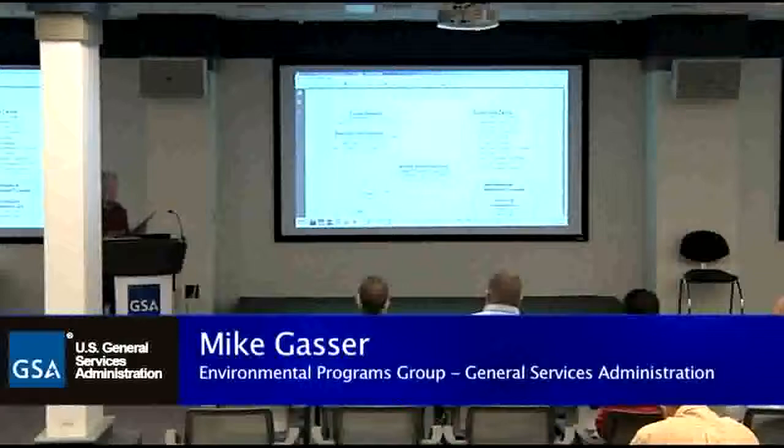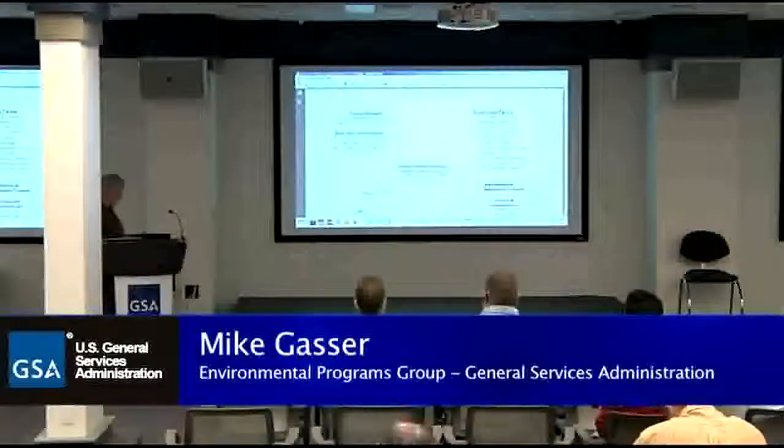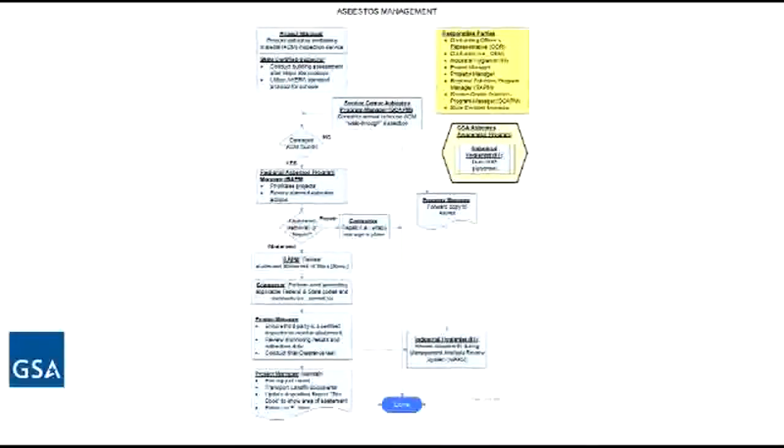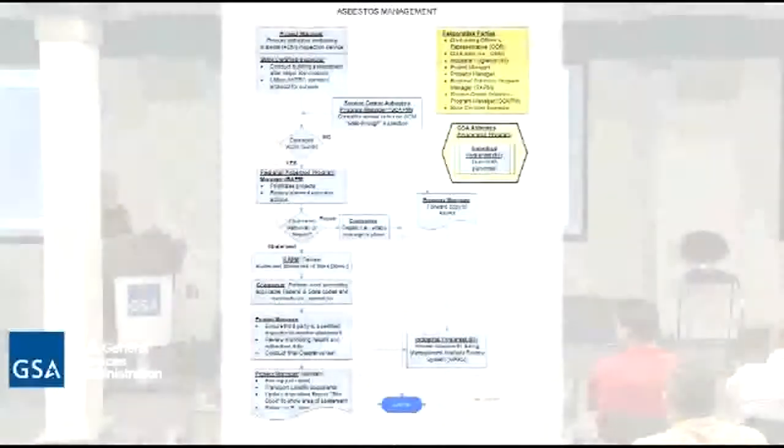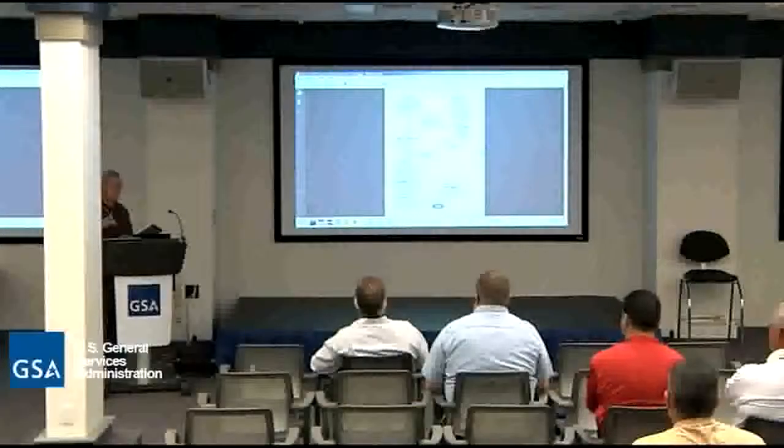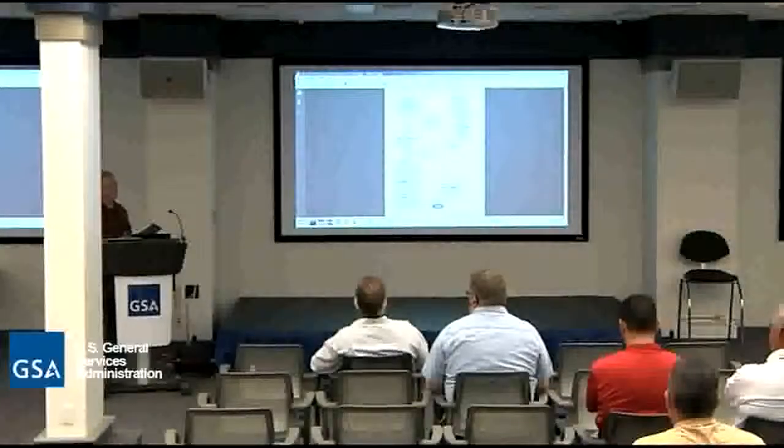Okay, I missed one when I went through, which was the asbestos management for buildings. One of the important takeaways on this is that all of the buildings should have an asbestos management plan. The asbestos management plan has the sampling of building materials within the building. The first look you should be doing on a construction job is to be looking at those plans to see if the area that you're working in has sampling and what the sampling results are.